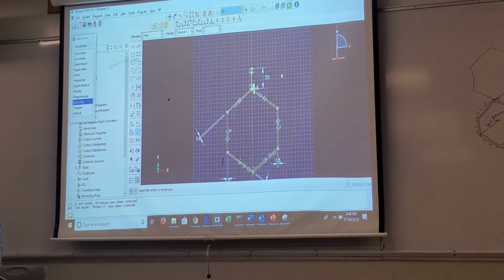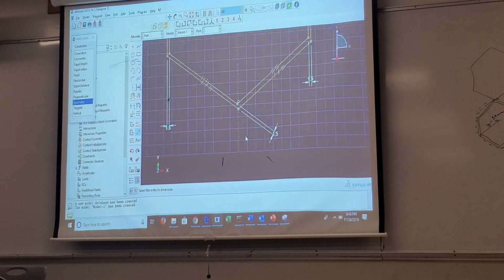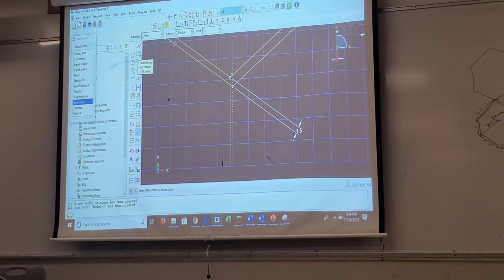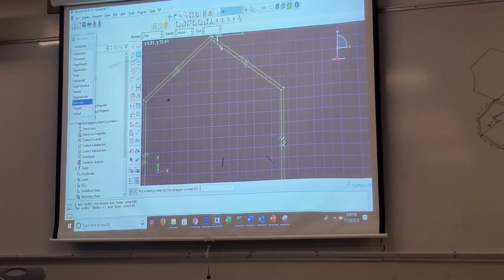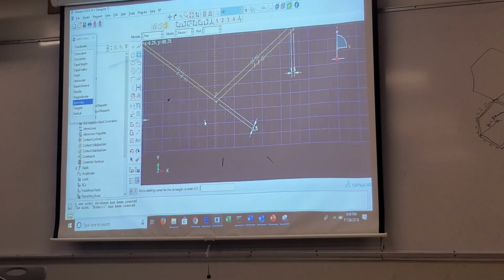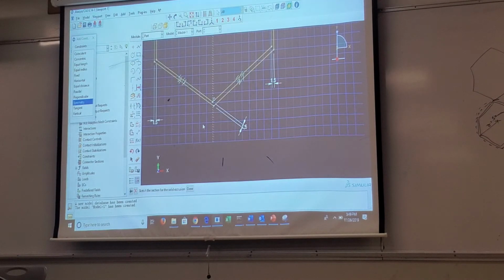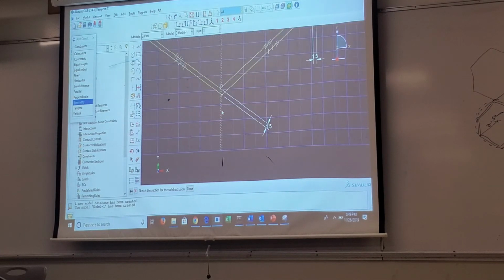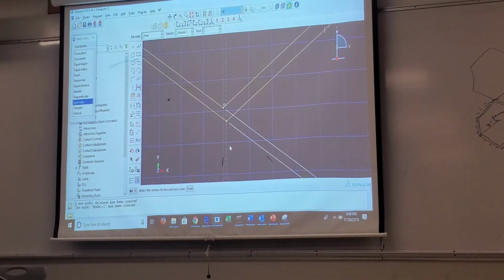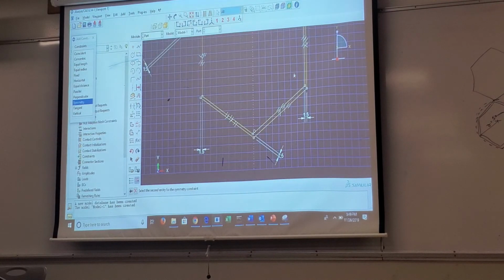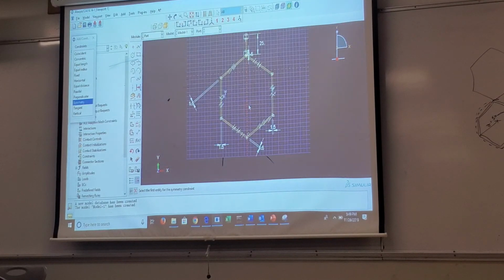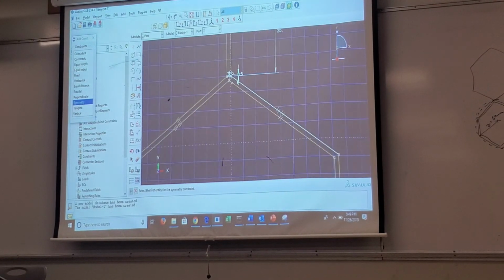The same thing you have to do at the bottom. Here you can create a mirror image, but if you have not followed the rectangle part, I am doing it again. So I am going to create a rectangle at the bottom. Do you trim the edge? One of the edges of the... No, we will do that later. So I am just making sure. So here, if you see my center line is slightly offset, so I also have to place a symmetry constraint here. So it's good now. Everything is perfect and symmetric.